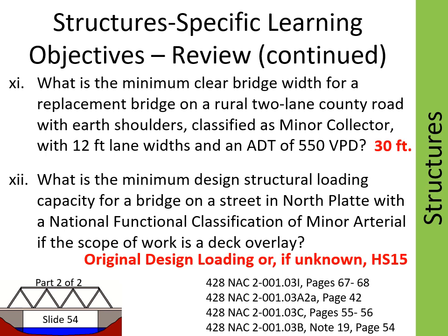A deck overlay is a 3R scope of work. See page 38 of the standards for 3R definition. Table C for structural capacity refers to note 19 on page 54. Note 19 indicates that for 3R work, the minimum structural capacity is the original design loading, or, if that is unknown, it would be HS15.